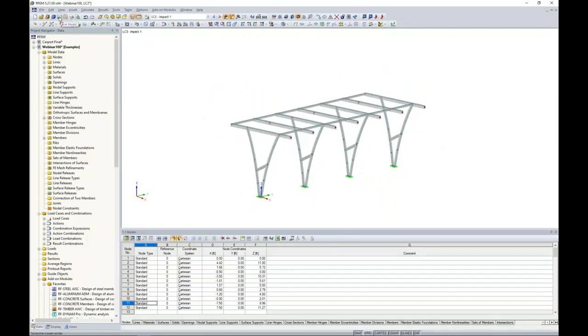Now, for impact load, this comes from ASCE 7-2016 and specifically section 4.5.3 for vehicle barrier systems. The code tells us that for impact loads, we should consider a 6 kip load applied anywhere between 1 foot 4 inches to 2 feet 3 inches above the floor.